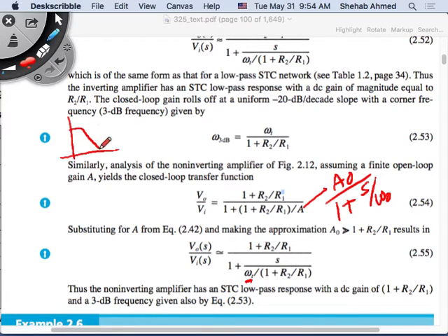So this was the low pass filter characteristic we have for the op-amp itself. It has a break frequency and it has a unity bandwidth frequency, FT. And we said that we can estimate A0 and the break frequency using omega t. If we assume that omega t is greater than omega, with these assumptions that we had, we can come up with a relationship between gain and FT. That's why this omega t appears in this equation here. And do the simplifications, this is what we're going to get.